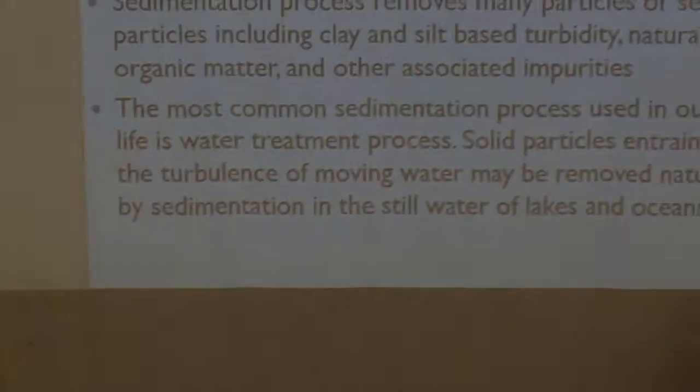Hello guys, my name is Sharifah. So now I will move to the first part, which is the introduction. Sedimentation is the tendency for particles in suspension to settle out of the fluid in which they are entrained. The flocs from flocculation move through large tubes. The water moves through these basins due to their large size. The flocs settle to the bottom of the basin due to gravity.